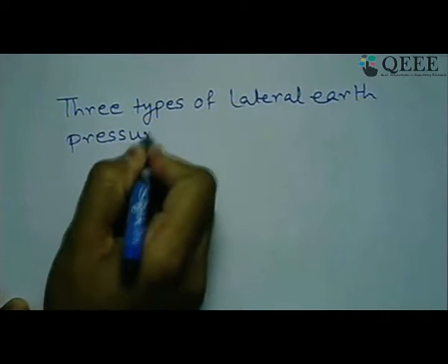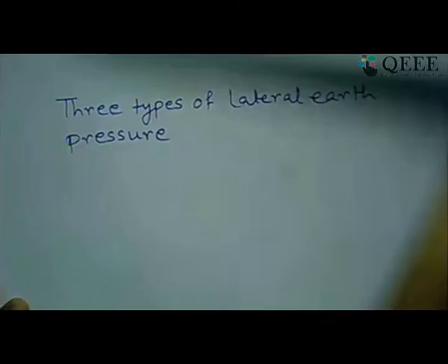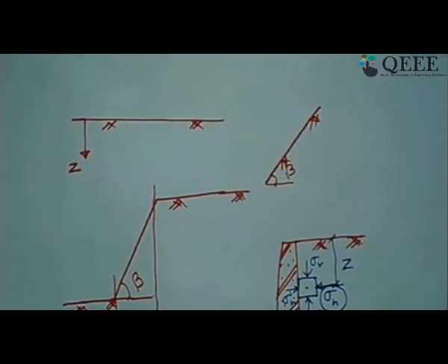Remember, in this case, one essential comment I would like to mention is that I am talking about a soil element. So this is a soil element. This sigma h, which I am talking about, the lateral stress or horizontal principal stress, is because of the soil material, not due to the water or any other thing.